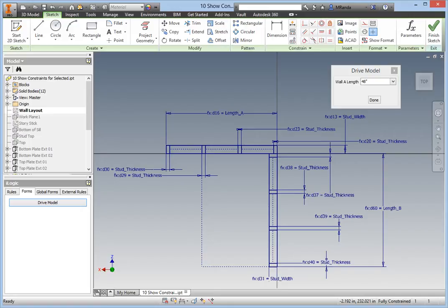The top line of wall A is where the failure happened, so check its geometric constraints first. Select the top line, and notice that besides the coincident constraints, which are represented by the yellow squares, there is a parallel constraint. Hovering the cursor over the constraint shows that the top line is parallel to the line just below it. No problem so far, so check the lower line. Here, you see the other half of the parallel constraint you just saw, along with a vertical constraint, which is fine, but the last constraint is problematic.